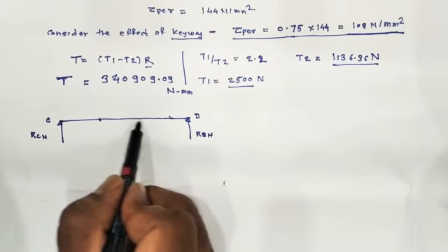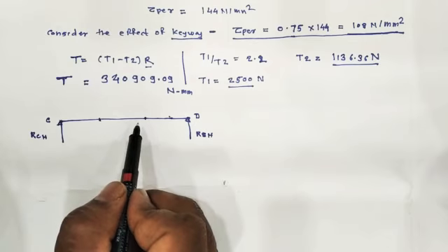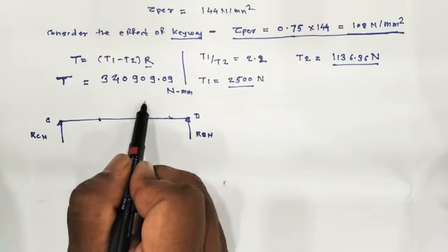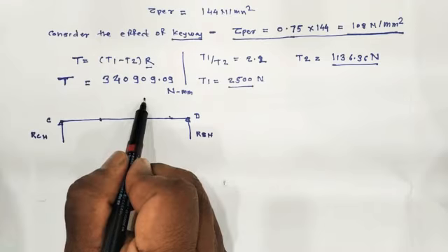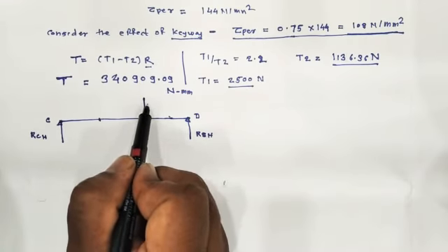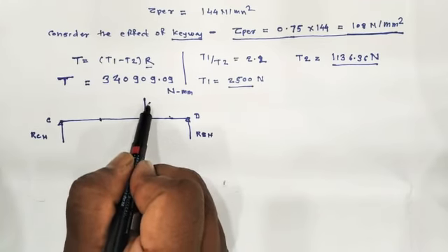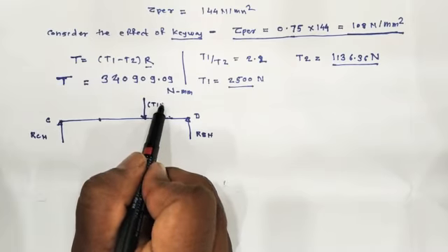These are the locations of the pulleys, and from the first figure we have pulley B transmits the power in horizontal direction. So only consider the pulley B here, and the net downward force for the pulley B is the summation of T1 plus T2.